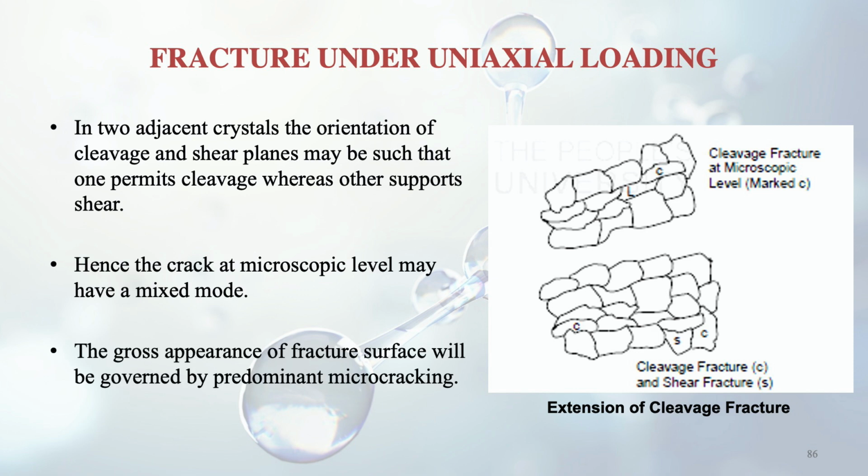The gross appearance of the fracture surface will be governed by the predominant micro cracking. Here you can see in the figure that the cleavage fracture and the shear are both shown. Depending upon which is more predominant, accordingly the shape of the crack will be formed.